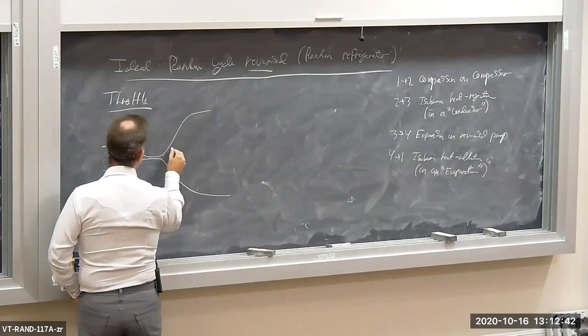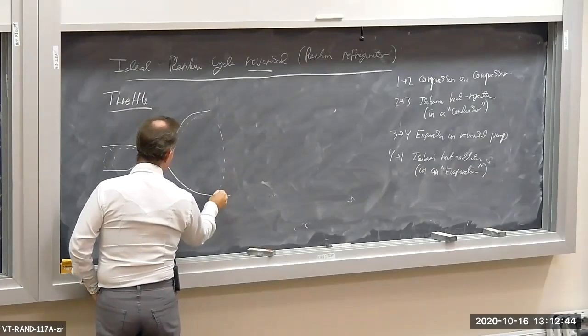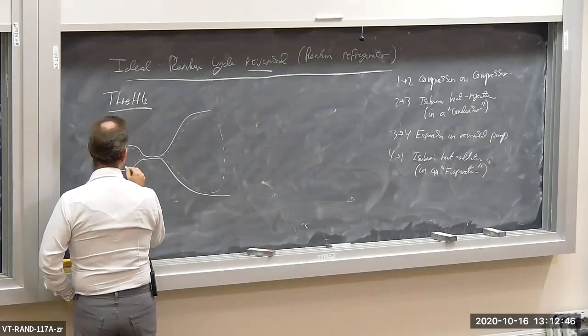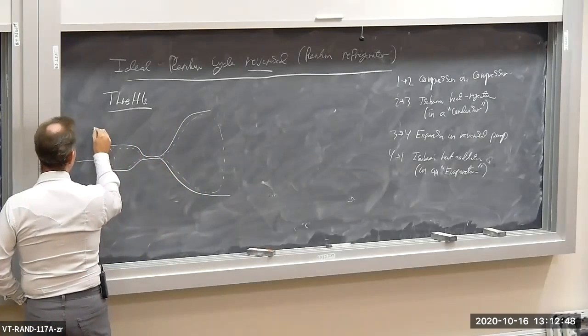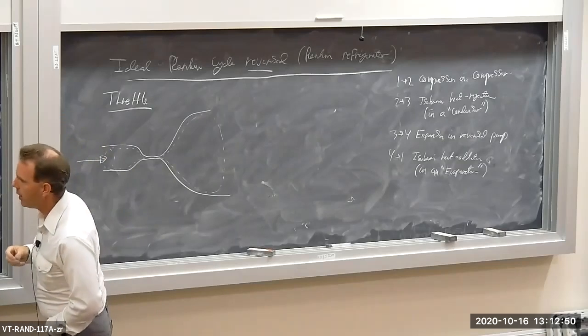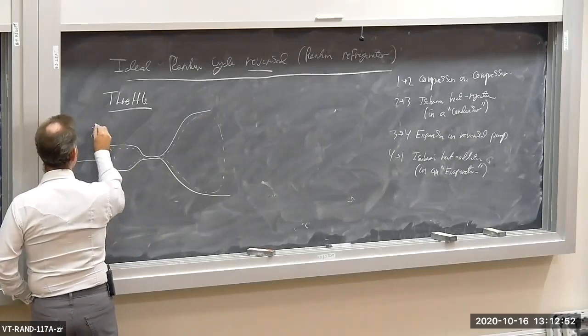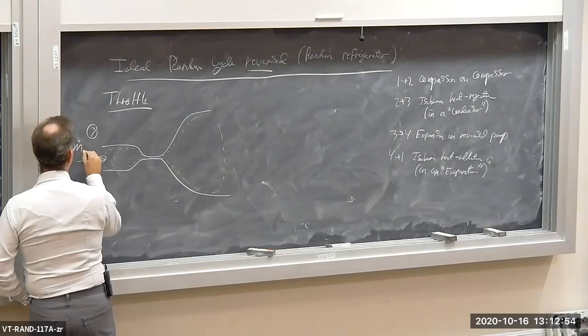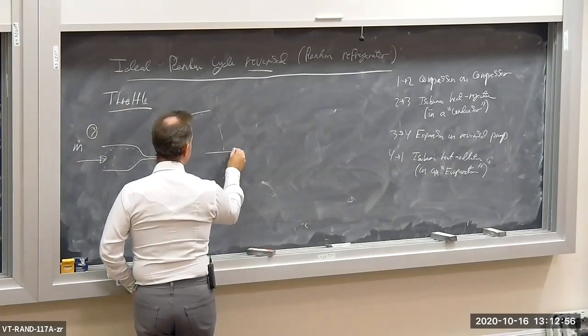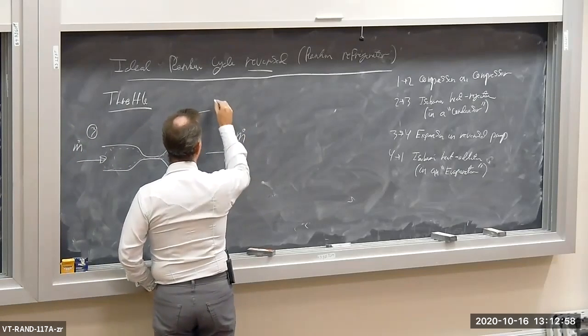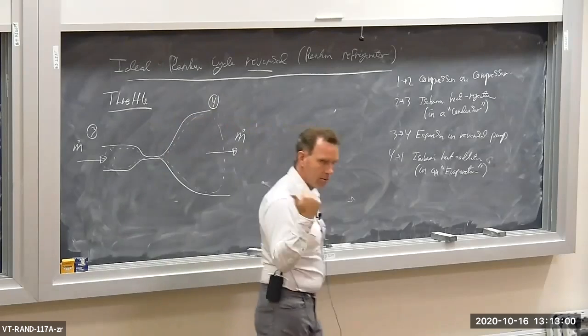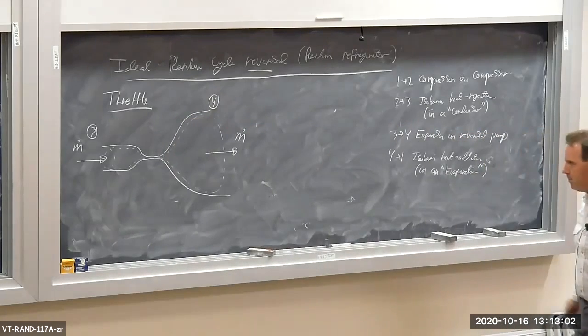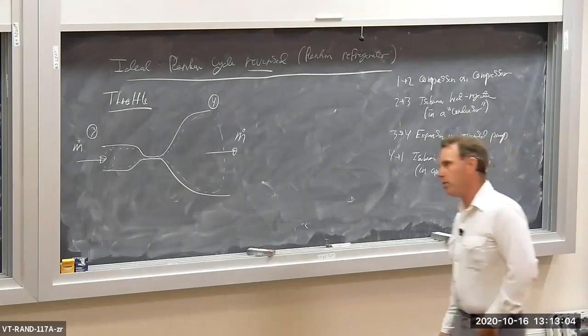So here's our control volume. Mass flow comes in at, in our case, location 3. So we have an m dot, and then mass flows out, m dot, and we end up with state 4, according to our diagram there. Now let's say this throttle is adiabatic.